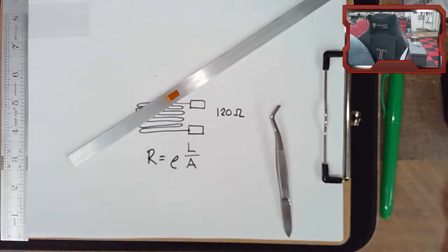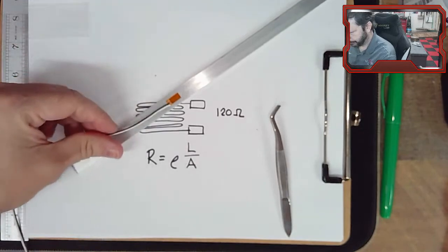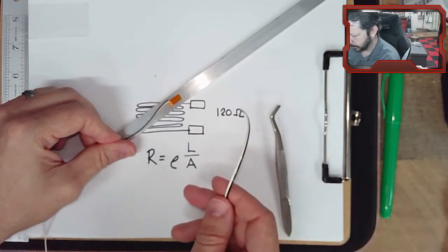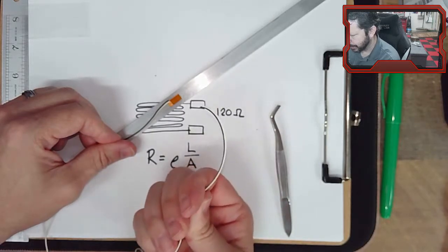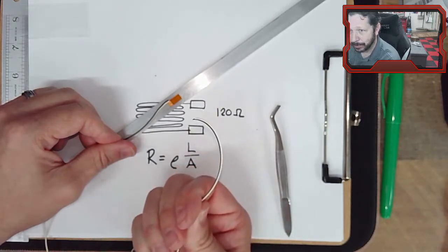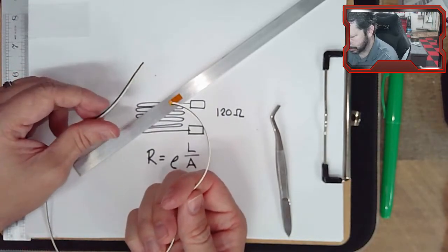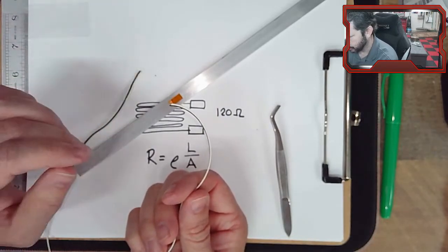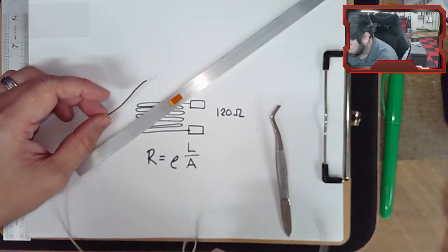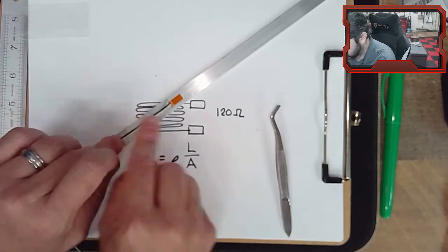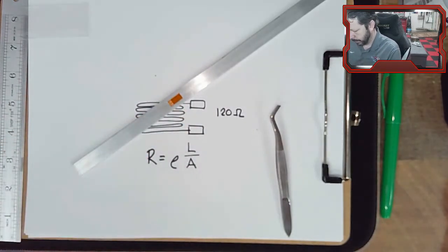And now I've got this little guy. And I can solder it on here, and the other end, right now it's going to be tough to plug this end into a breadboard, so I'm going to have to go in and tin the ends of it, or maybe connect it to something that's easier to plug into a breadboard, but we'll worry about that part later. Right now we need to get this guy in this position and these wires stripped back so that we can actually solder.